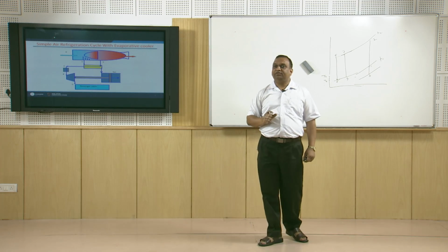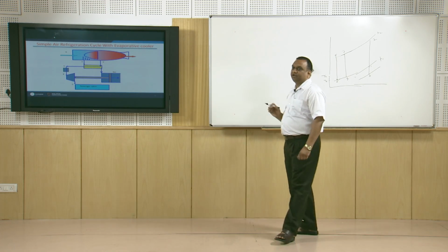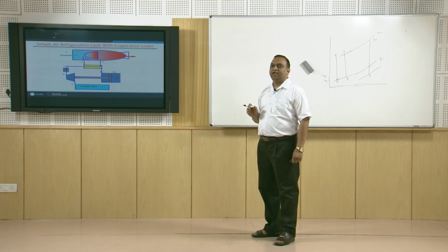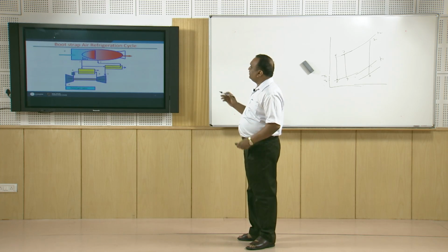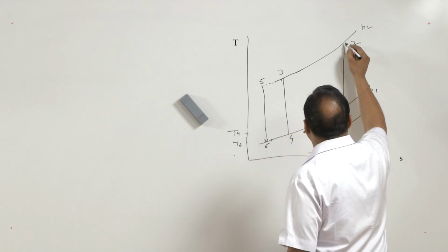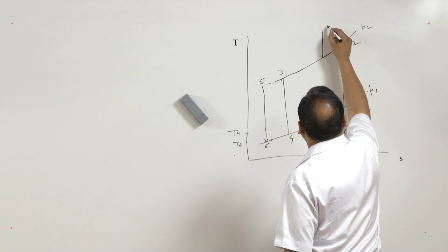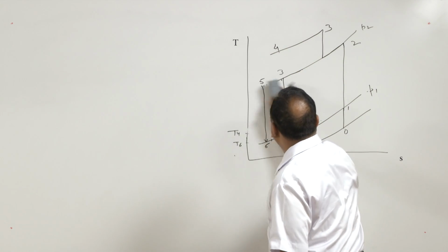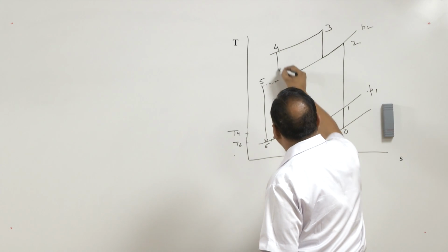In this case, we get a cooler air entering the passenger cabin, or we can say the same amount of circulated air can take more refrigerating load. Same arrangement is made in the bootstrap cycle. In the bootstrap cycle, you know, there is a two-time compression, first, then second compression 3, and then cooling 4, and 4 to 5 expansion takes place.